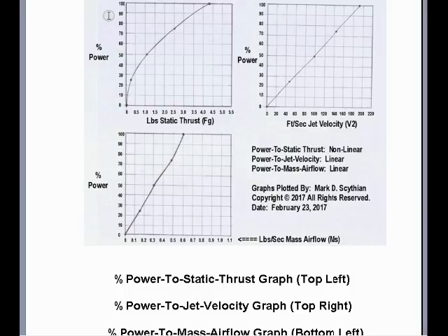So the graph quantification on the thrust component, the static thrust component, is definitely not linear, but once you derive this either through polynomial recalculation, graphic method, or differential equation, you now have a very convenient graph to know where to set your power for a desired thrust component.